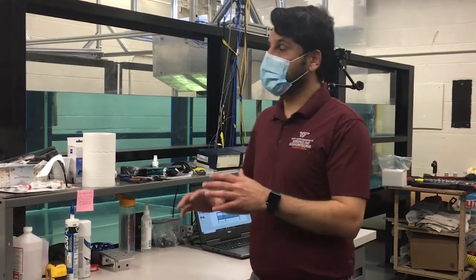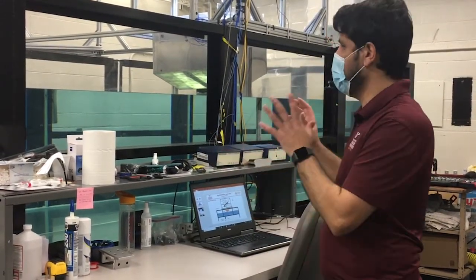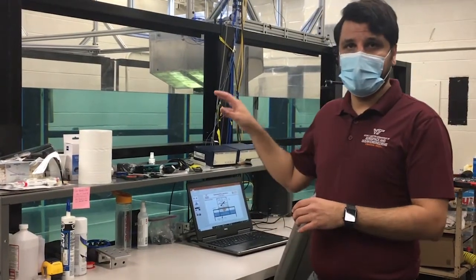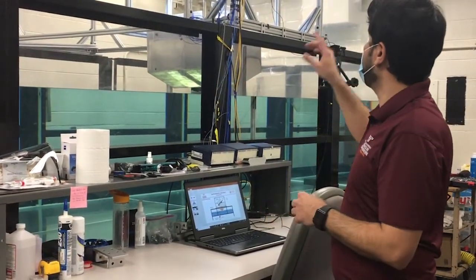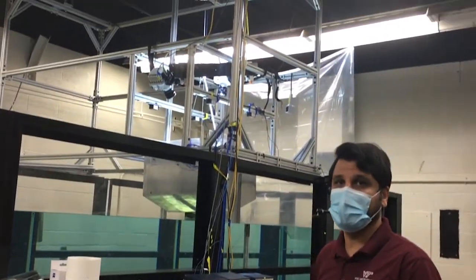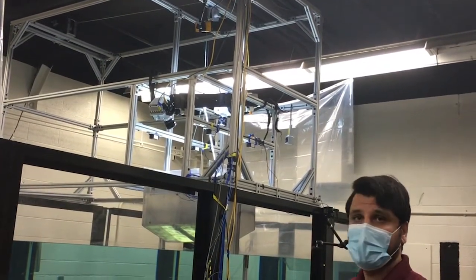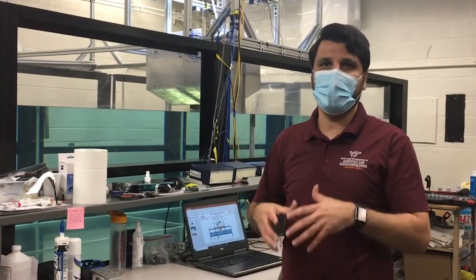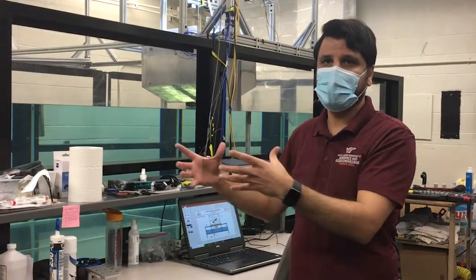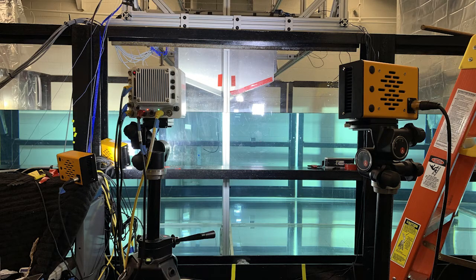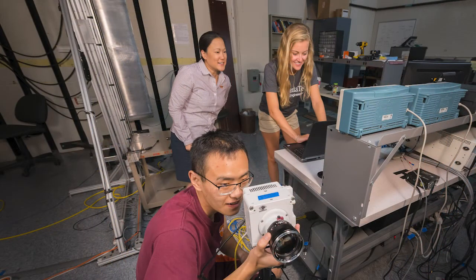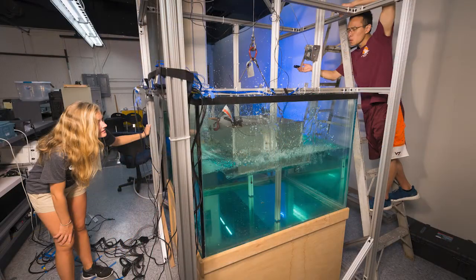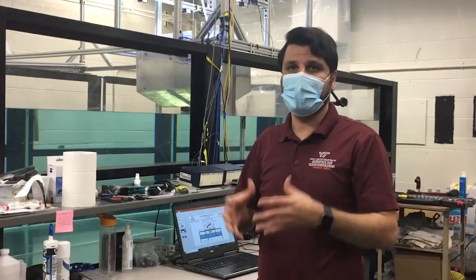have flexible bottom structures. So for that, we have this great big tank here. It's made of acrylic sheets. It's transparent, so we can see through it. We have a setup which is made of 80-20. It is located on top of the tank. This setup provides us with the pure vertical motion. So we can have different models. We can drop them using those two guide rails that are already implemented into the setup. And we can test different aspects of the water entry, or the impact of the model with the water.